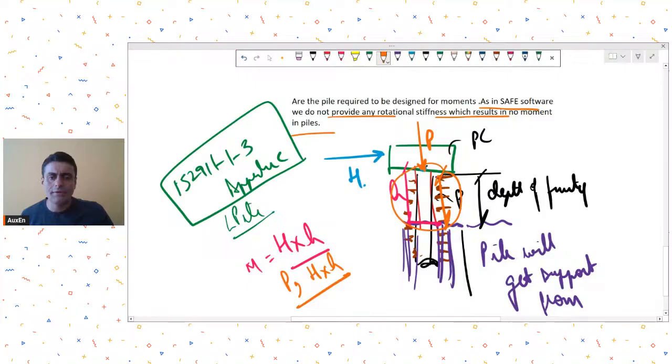Below that, because we are assuming it to be supported, this is the length of pile that is assumed, and then you can design this pile for combined axial load plus moment. Many design engineers will use SP16 curves for it, or any other alternate column design procedure for this type of pile arrangement also.